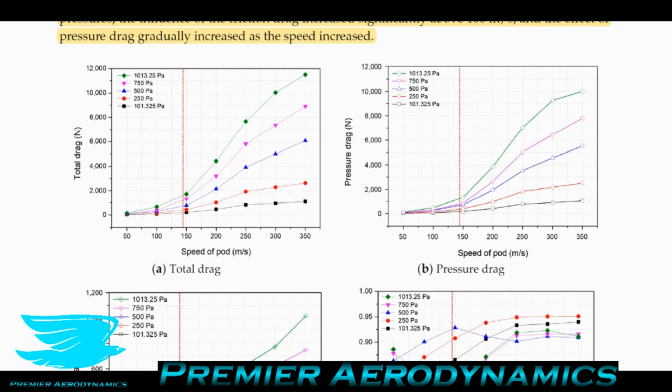How you would do that is kind of up to the researcher. You can specify what you would do, but one way would be just to look at the additional drag increase due to the increase in velocity because of the shock. So in this paper, they're just talking about the pressure drag in total, but that can be divided into the wave drag plus the traditional pressure drag. The wave drag just hides itself in the same general physics as the pressure drag in terms of changing the pressure on the surface, through which all force is propagated.